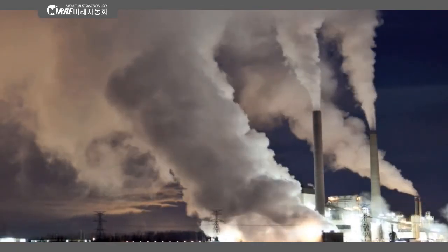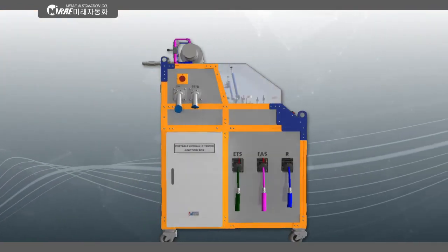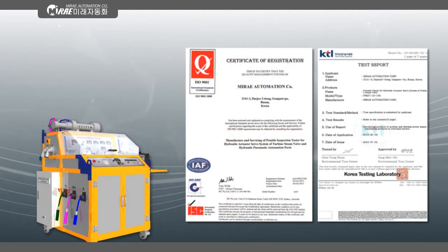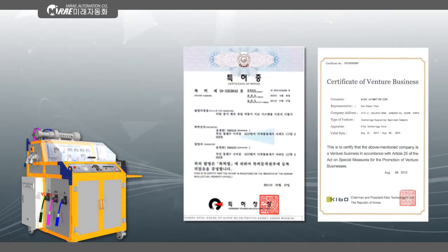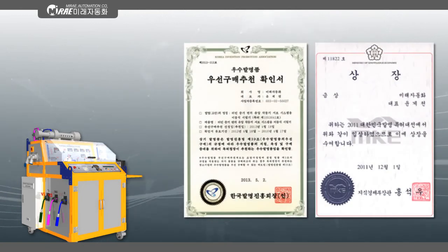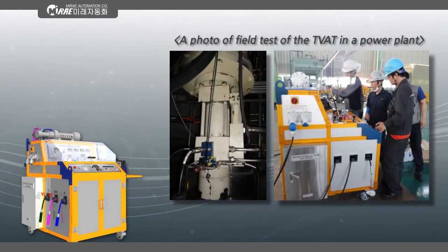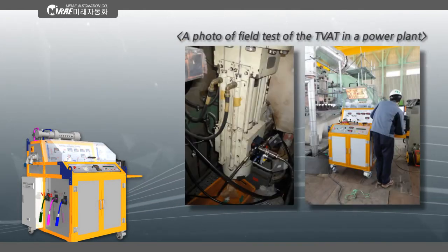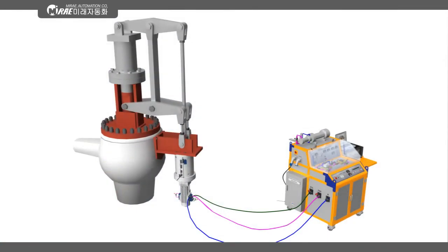The Turbine Steam Valve Hydraulic Actuator Tester can improve the current problems in diagnosis and performance test of turbine valve actuator. That is an important device for controlling the amount of turbine steam in thermal and nuclear power plants. Turbine Valve Actuator Tester is a portable tester applying in workplaces without detaching turbine valve actuators from the hydraulic system line, and provides the reduction of maintenance time and overall performance diagnosis for the sake of steadiness evaluation and reliability of maintenance of turbine steam valve hydraulic actuators.